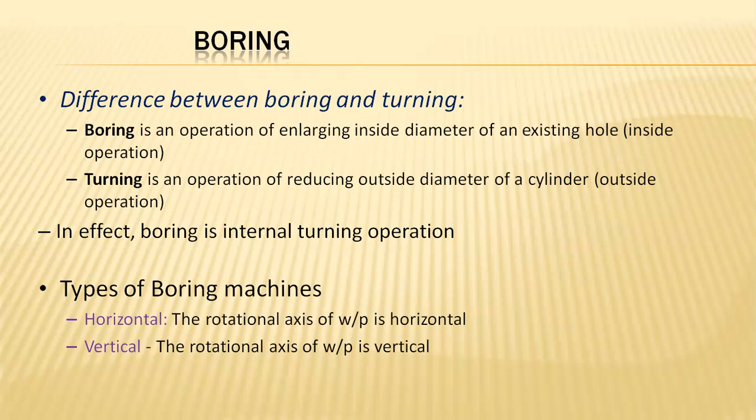Let us consider the basic difference between boring and the turning process. Boring is the operation done for enlarging the inner diameters of existing holes, whereas the turning operation is used to reduce the diameter of work parts, and also for knurling, threading, and step cutting operations.